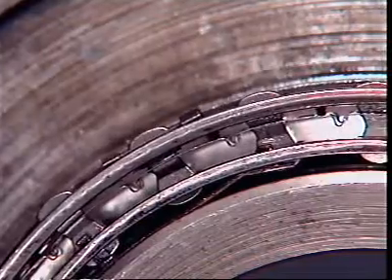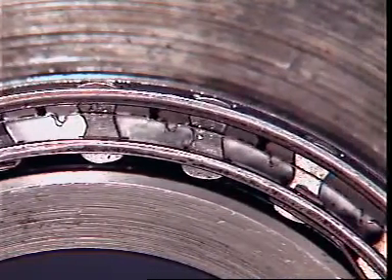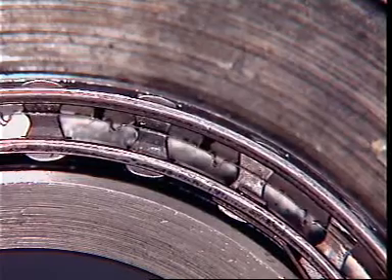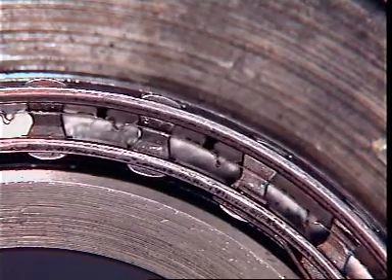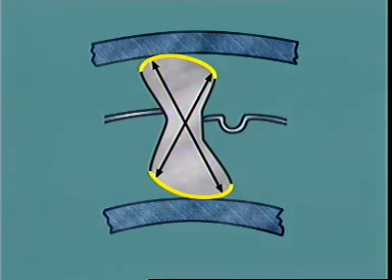The cage moves the sprags together so that when the stator is locked, each carries an equal share of the load. The one-way action is produced by the different radii of the sprags and the curvature at their outer edges. This gradually increases from the shorter radius to the larger.